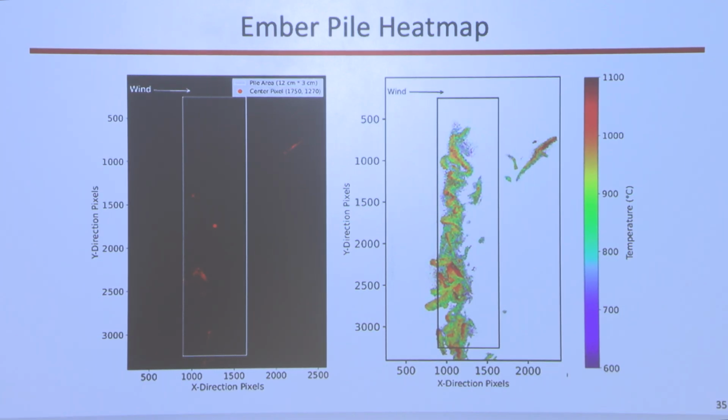We don't show the emissivities, but we have them as well. Or actually, as an alternative, you can just assume a constant emissivity. Here we're using a constant emissivity of 0.8, and that seems to do a pretty good job. And then we'll map all these temperatures with the shape factors back to estimate the heat flux at the heat flux gauge.